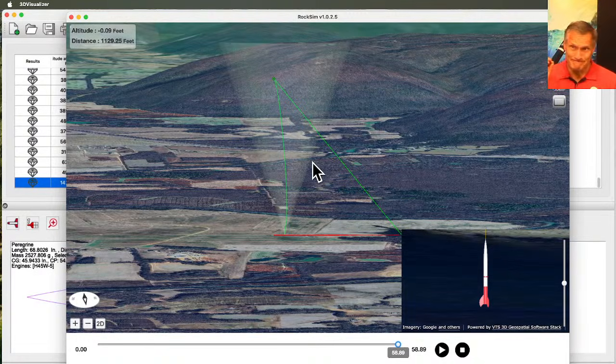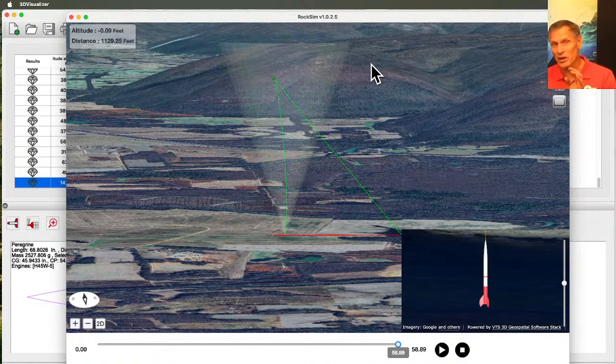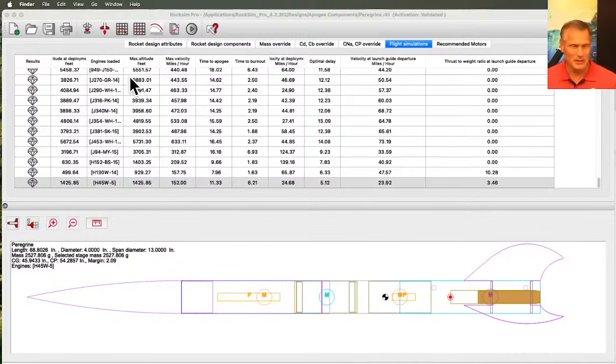So based on this, there is the possibility that if you're willing to risk it, the rocket will still go straight with that particular rocket motor. So even though its thrust to weight ratio is not quite 5, the trajectory looks still pretty straight. Now the question is, do you trust it? And that I can't answer because that's something that you have to determine yourself. But hopefully that explains thrust to weight ratio for you.